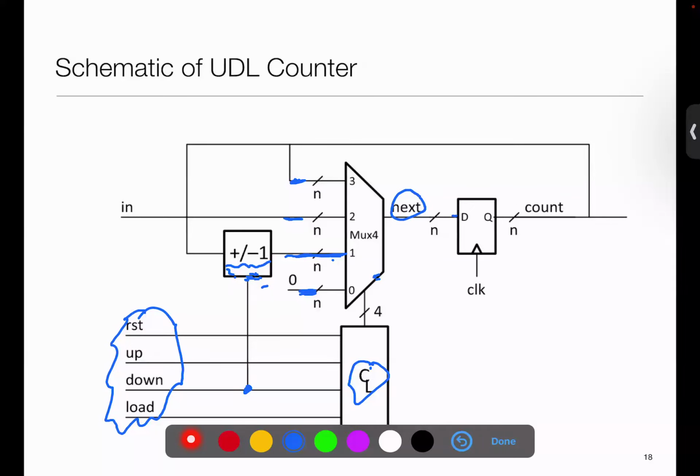So anyway, this is a structure. So as you can again see that the heart of a data path is registers which hold the variables, multiplexer which let you select between different cases, and then some logic which truly decides what is happening. And then also we will need some side logic which will control the multiplexers or provide extra inputs to the logic blocks out here. Okay, so there's a very typical way data path looks like.